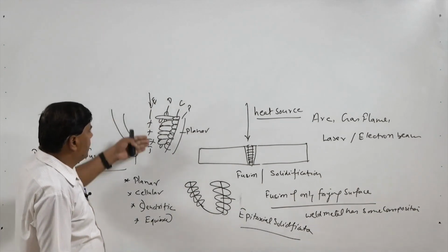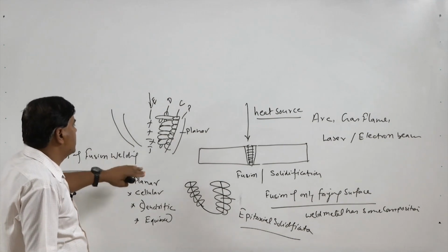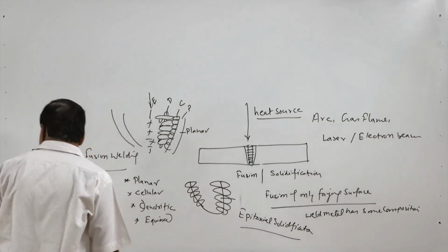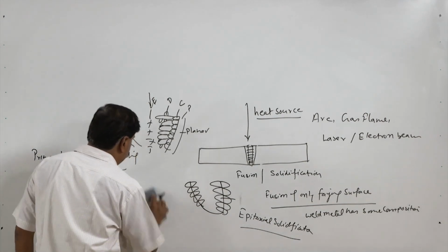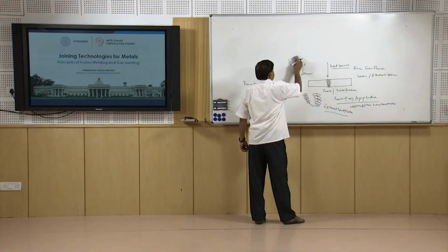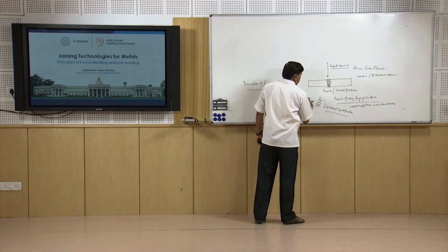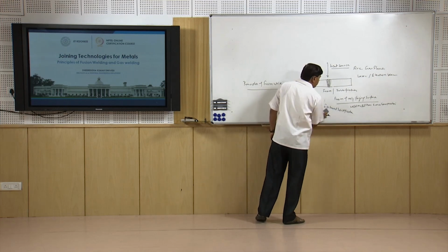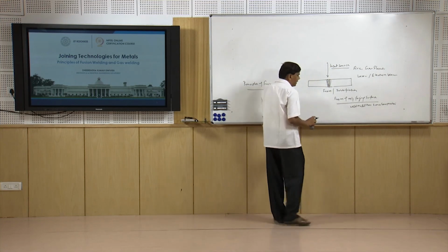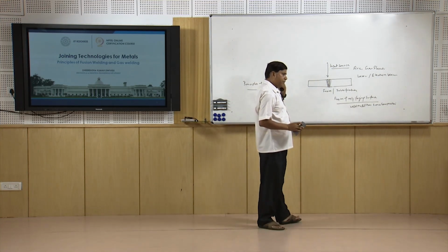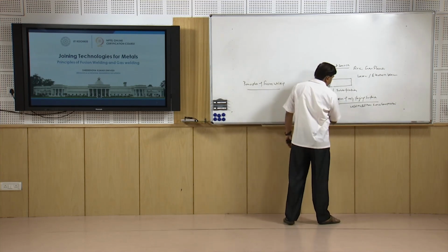It is always preferred to have the equiaxed grain structure, and therefore, to achieve this equiaxed grain structure, compositional modifications are carried out. But if the weld metal composition is different from the base metal, then first the nucleation on the fusion boundary takes place, thereafter the growth occurs. So, that is typical nucleation, and the growth modes are involved, steps are involved for completion of the solidification.